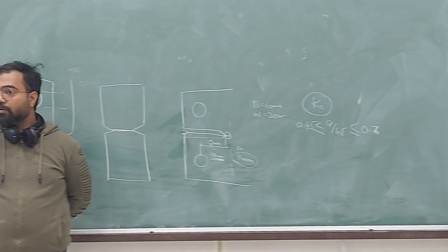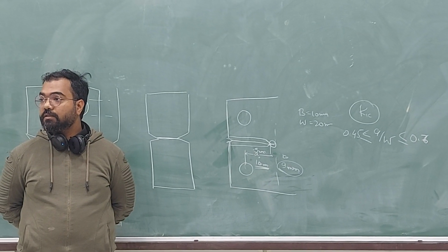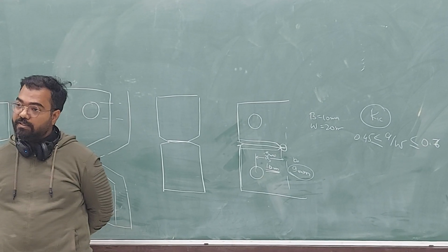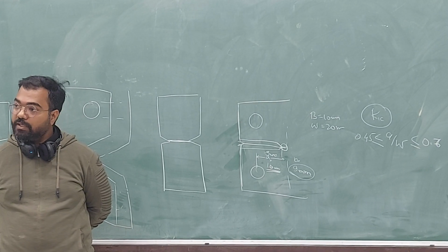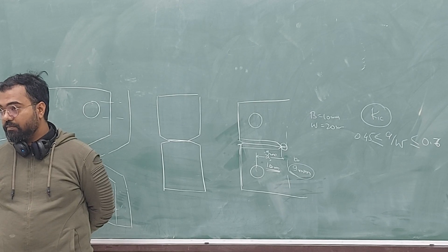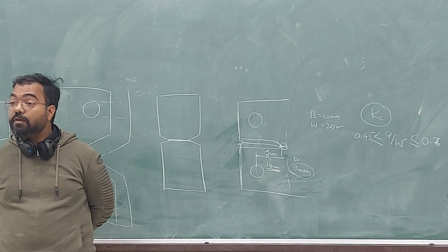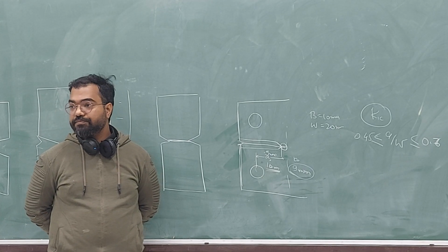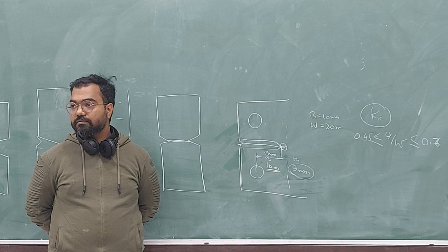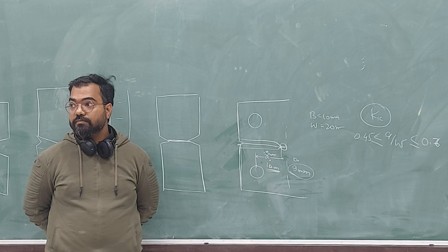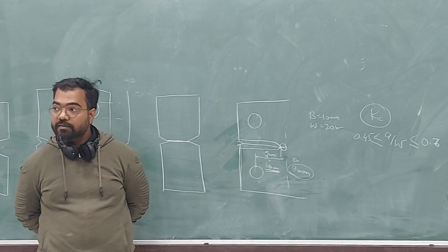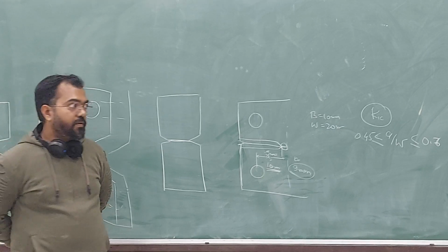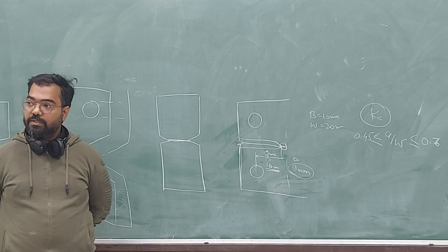Okay. So whatever you do, you can't really be in the high cycle fatigue region. You can't, because there is a notch. So there will be a plastic zone. Okay. So somewhere it will be in the low cycle fatigue region. So stresses are going to be high, but you are not supposed to have the stresses very high. Why? Yes, it will. Go ahead. The notch will not be sharp. No, it will be sharp.